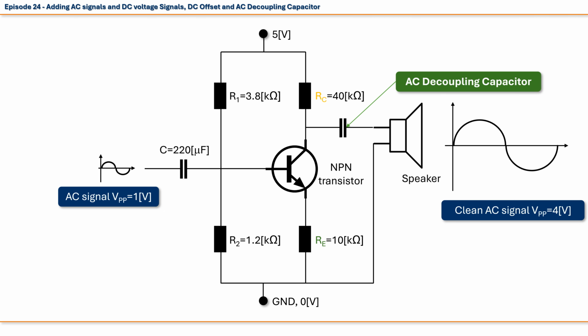Now, if you are not familiar with the relationship between capacitors and AC signals, suffice to say that when capacitance of a capacitor is carefully selected, the capacitor lets AC signal run, while blocking any portion of DC offset. A capacitor that fulfills this role in a circuit is called an AC decoupling capacitor, as it divorces AC signal from its DC offset. Once DC voltage fully charges the capacitor, the capacitor presents an open circuit to DC voltage and current, while letting AC signal run freely.